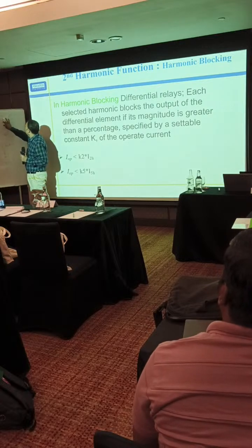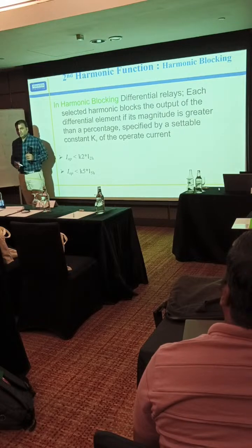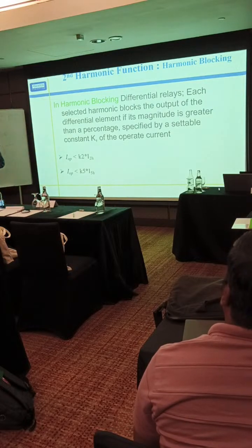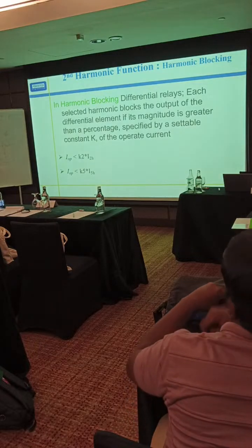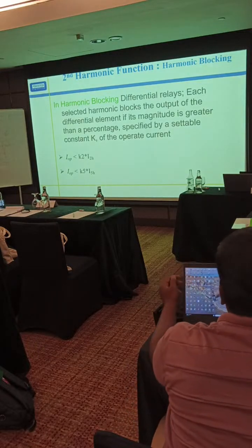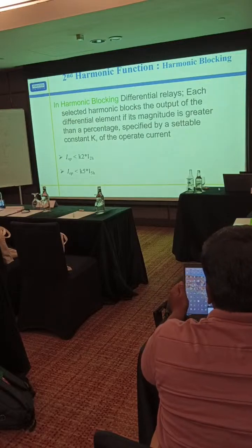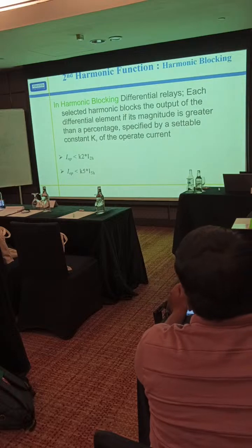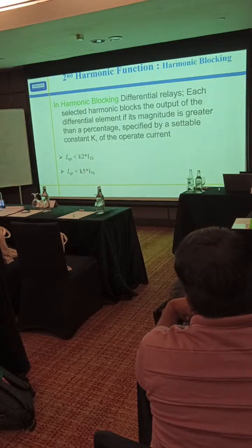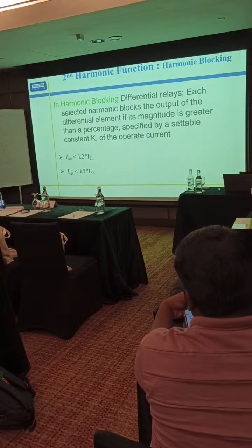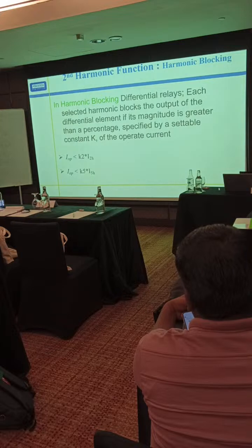So you need only 6 current, or there are different methods, many ways you can test this harmonic testing. I explained 3 methods for how you can test. But the basic one to understand is you have 6 current, you can reduce one with the second harmonic component and keep the other constant.